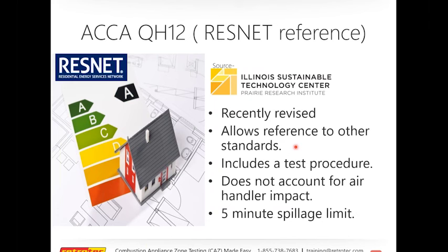It does mention BPI. It mentions NFPA, and it does mention the ACCA one. ACCA QH12 does include a specific test procedure. It does not account for the impact of the air handler, but the bottom line is, and I'll explain this more clearly in a minute, it does call for a spillage limit of about 5 minutes, and we're going to find that that's pretty common across most of these.